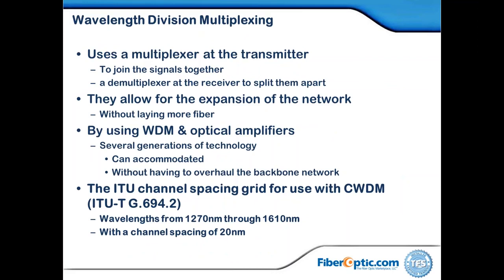and we can communicate. Now that brings us to a basic thing of fiber to the home, is the fact that I can downstream video and at the same time uplink my other services over a single fiber. The fact that the upstream services aren't running on the same wavelength means that they will not interfere with each other. Now later on, since typically they might split to 4 homes off of one fiber as they come down your street,